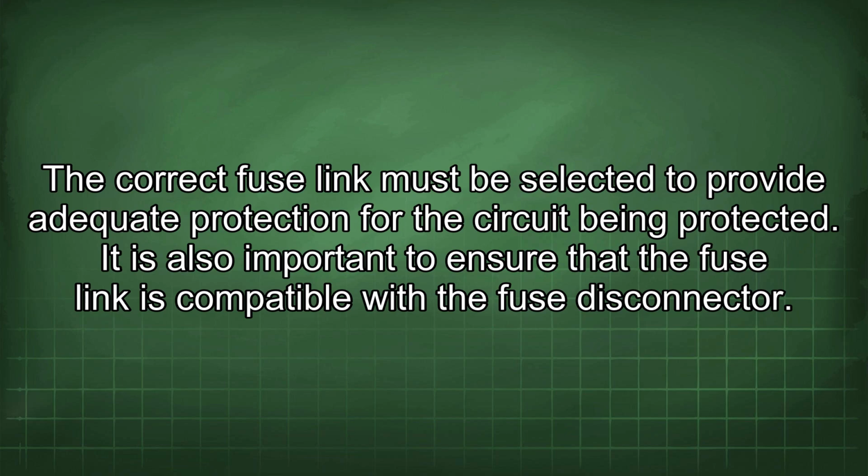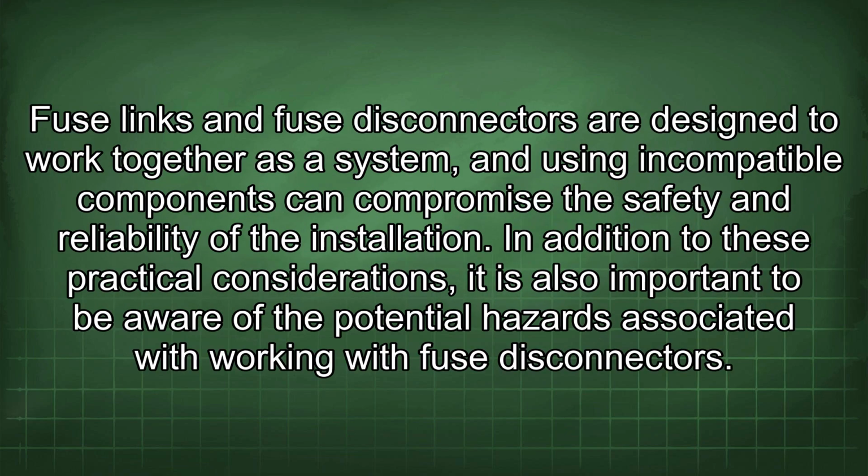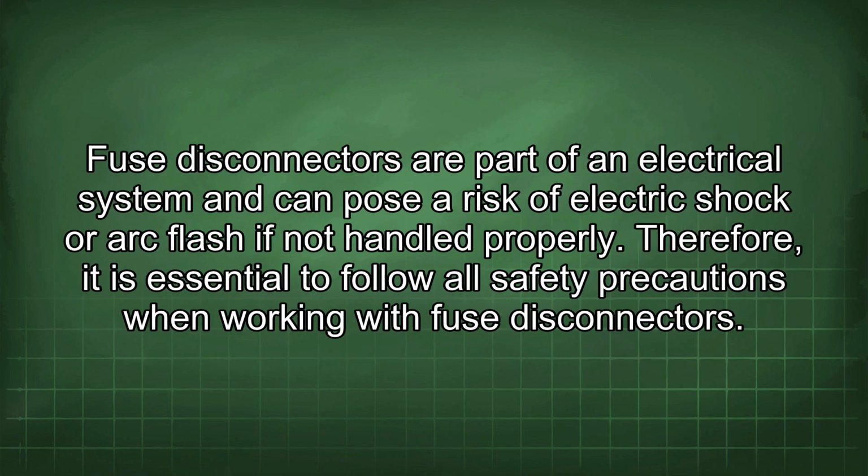It is also important to ensure that the fuse link is compatible with the fuse disconnector. Fuse links and fuse disconnectors are designed to work together as a system, and using incompatible components can compromise the safety and reliability of the installation. In addition to these practical considerations, it is also important to be aware of the potential hazards associated with working with fuse disconnectors. Fuse disconnectors are part of an electrical system and can pose a risk of electric shock or arc flash if not handled properly.